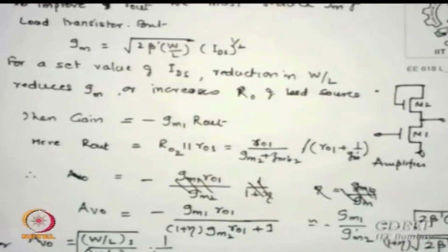As I say, we can also use other loads for amplifiers. The other load could be what I said the other day: just by putting an N-channel transistor and biasing it, that means if this transistor is biased heavily by me such that VGS minus VT is always greater than VDS, the transistor will remain in non-saturation, so linear mode, a smaller resistance. And how will I adjust that value? By W/L. So again by using a W/L and keeping VGS minus VT larger than VDS for the load device, I can control my smaller values of resistance.